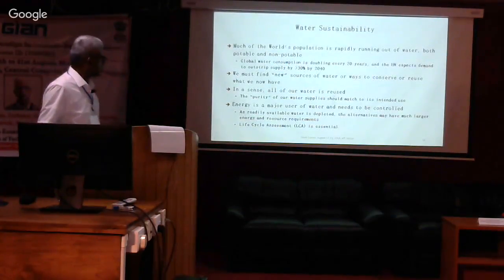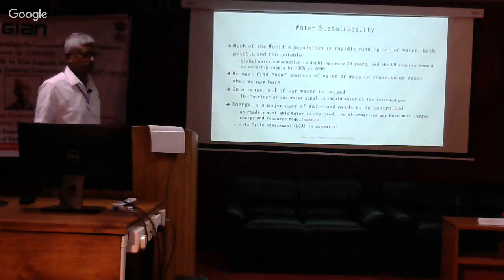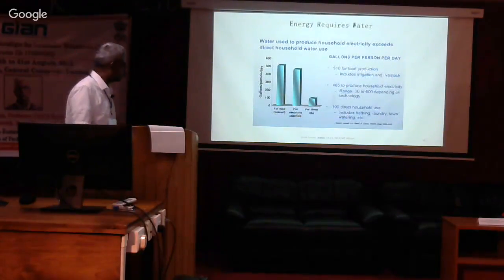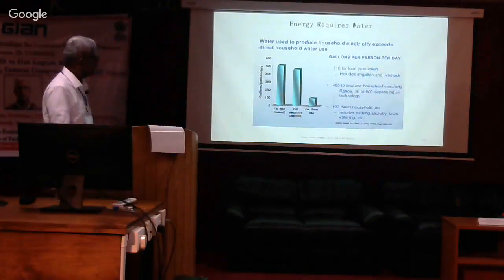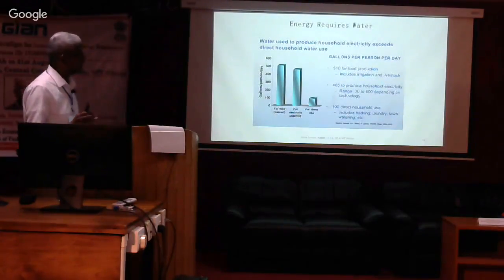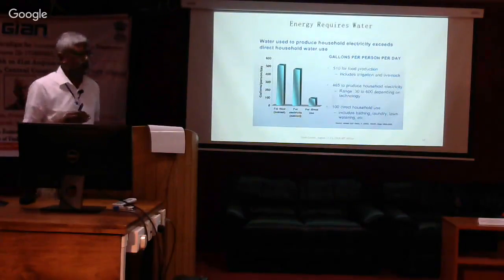That's the idea. And as I said, I very much would have liked to include this LCA, life cycle assessment, but unfortunately we won't be able to do this. Okay, so energy requires water. How much? Now I don't know in India. The number that we typically use in the United States is 100 gallons per person per day. This is for our design purposes. 100 gallons is about 385 liters. So in India, it's much lower. I don't know how much lower.